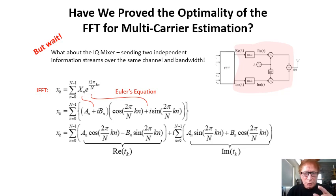But wait. Recall the standard OFDM mechanization of the transmitter and receiver. For all OFDM designs, there were in fact 2 time history measurements, one for each of the IQ mixer outputs, as we show on this slide, top right. For 802.11a with 64 subcarriers, the IFFT is initiated with 64 AB pairs from the QAM constellation. The time history output of the IFFT is the real and imaginary results from the IFFT, or 2 separate time histories.